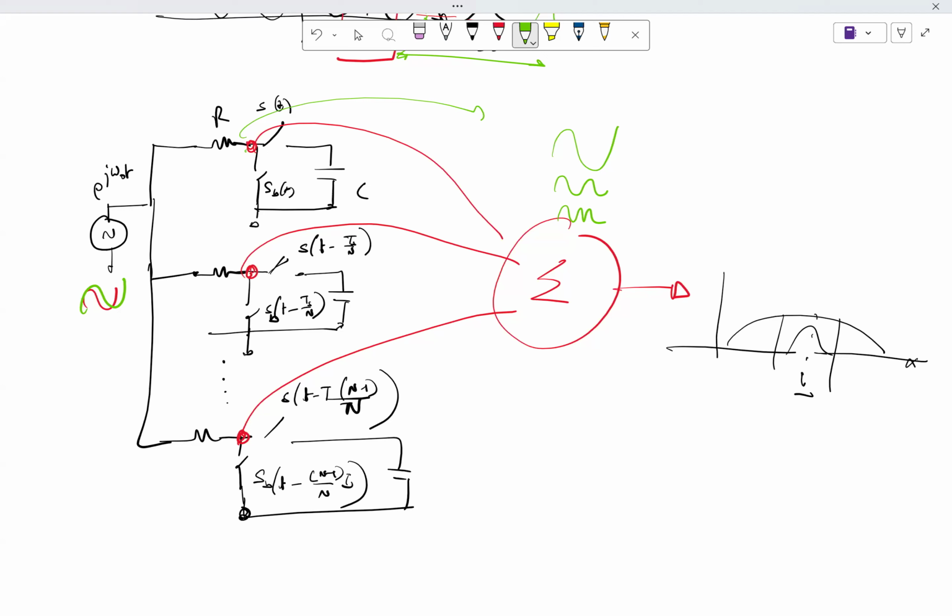But if you have 4 of them together, or n of them together, you are not going to get this. This will not be there. This will not be there. The next thing that will be there will be n times higher frequency. Which means that I take this out and put a bandpass filter around omega s, and this bandpass filter can be very lousy, like it can be maybe going to 0 around 4 omega s. That itself will suffice. But if I only have one kernel, this lousy LTI bandpass filter has to go to 0 at 2 omega s.